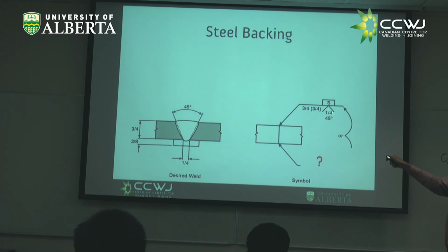1/4. This 1/4 here is the root gap. This is the root gap here, and this 45-degree is the groove angle. So now we're saying a whole lot of things, right? And what we're saying here, 3/4 and parentheses 3/4, in this case wasn't necessary.